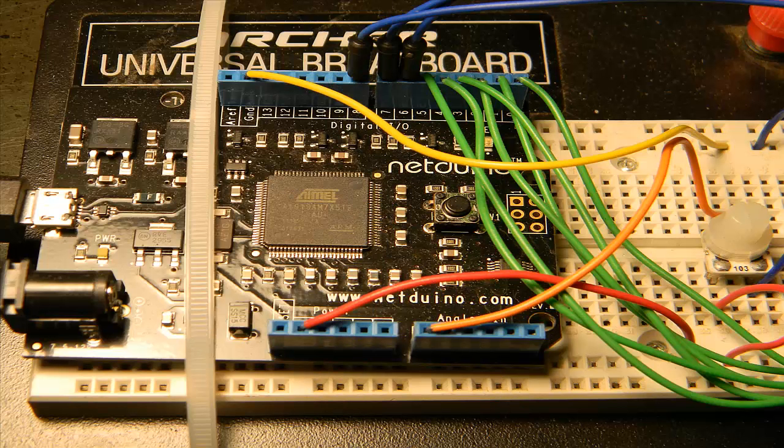In this slide we have a close-up which shows how some of the cables are connected to the Netduino board. You'll notice I have the power connected with the red line. The yellow line is connected to ground. That's connected to a different plane on the prototyping board. The orange wire is the analog input that's connected to the potentiometer. The green lines are connected to the LEDs for the standard single color LEDs. The blue wires are connected to the poles of the 3-color LED so that I can turn the colors of the individual LEDs inside the 3-color LED on and off.